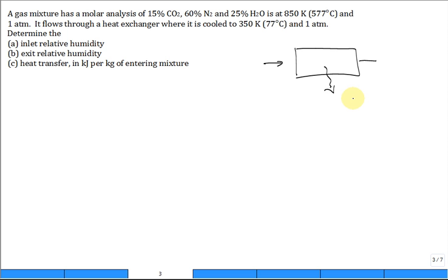So there's some Q dot out, true. And we have, either on a mass basis, you could talk about the mass flow rate or the molar flow rate. You could talk about the mass flow rate of each constituent, the molar flow rate of each constituent, where you'd sum i equals 1 to 3. And it comes in at temperature 1 and goes out at temperature 2. We always think about when you're cooling some air, you may want a drip pan in case there's some liquid condensate that may come out. True. So often you would put it like this.